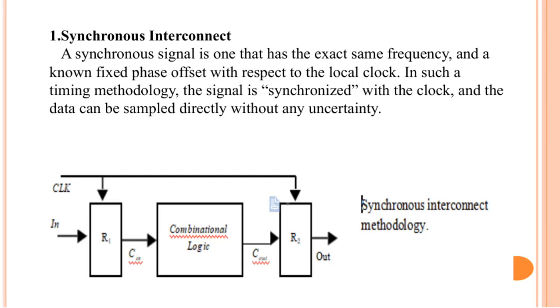Here, we're talking about synchronous interconnects. What this means is that the signal we're dealing with operates at the same frequency as the local clock, and it maintains a fixed, known phase relationship with that clock.